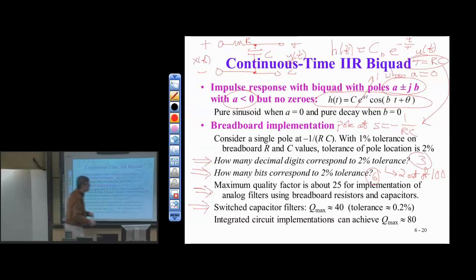That we really want to put the biquads that are tending to oscillation last. So in terms of how we put the biquads in order, we want to go from low quality factors on the input side to high quality factors on the output side. So from left to right, from input to output, we want to put the biquads in ascending order of quality factors. And the idea is that if we put the stages that have decay in them early on, we clamp down the voltage range, which will cause us to have less oscillation later, because that oscillation happens at the end, not at the beginning.